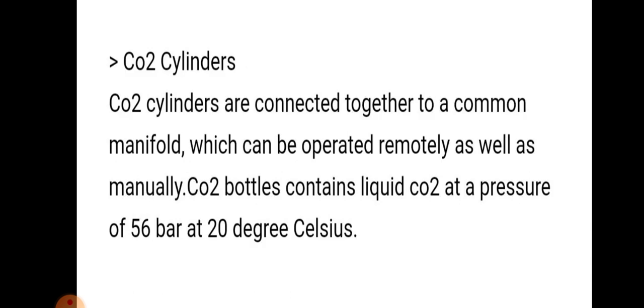CO2 cylinders are connected together to a common manifold. They can be operated remotely as well as manually. A CO2 bottle contains liquid CO2 at a pressure of 56 bar at 20 degrees Celsius.